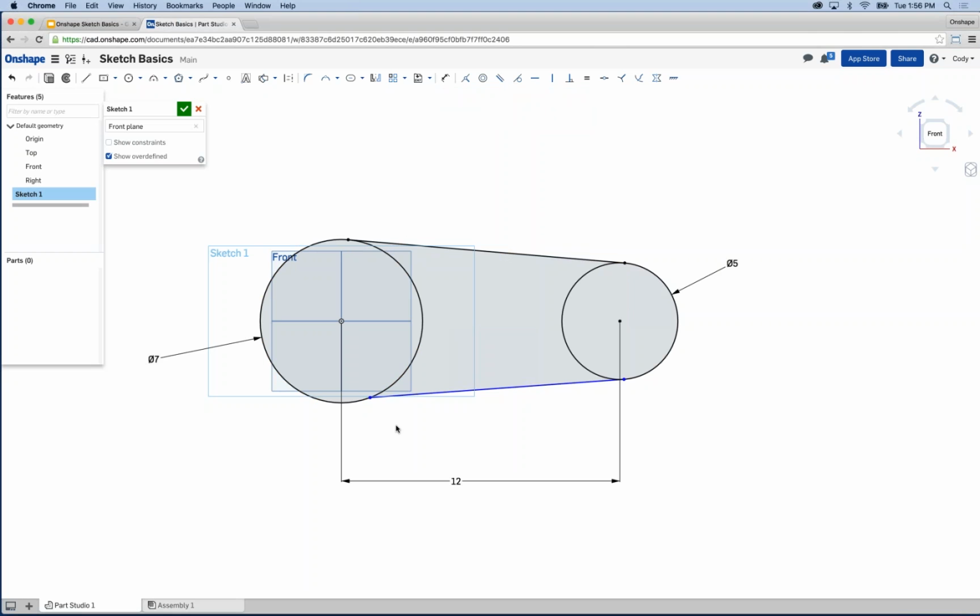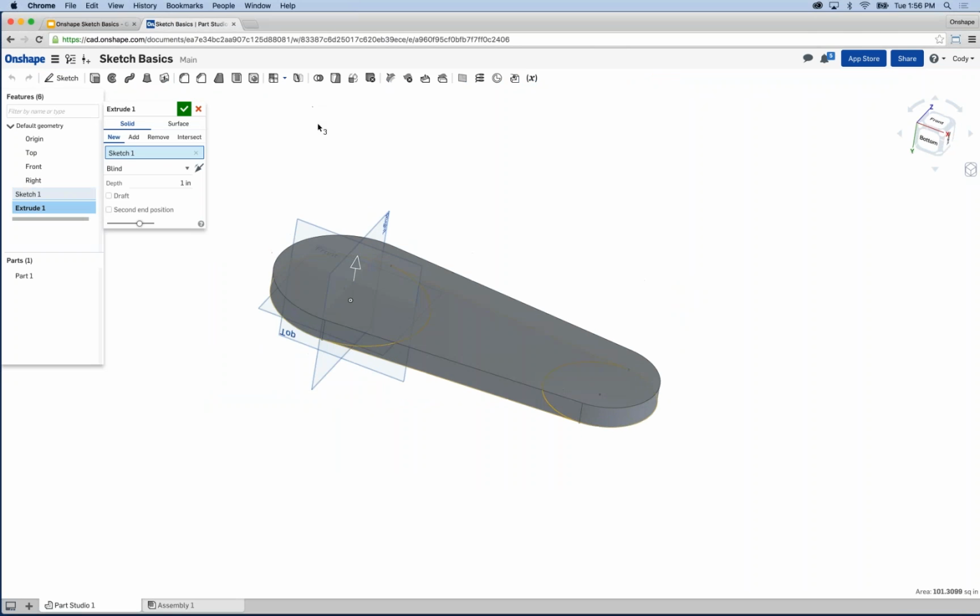Okay, so again, let's do that one more time. Left click the line, left click the circle, then select tangent. Okay, so again, we're using a combination of dimensions and constraints. Now I've gone to a fully defined sketch here with 3 dimensions and a few manual constraints that I had to add. And now I can take this and turn it into a 3D feature, and extrude, revolve, sweep, loft, whatever it is that I'm trying to accomplish. But again, visual cues, and the key thing with our sketches is we want to make sure that we're correctly constraining them and that they correctly reflect our intent.